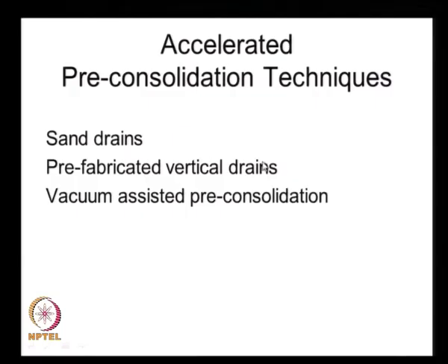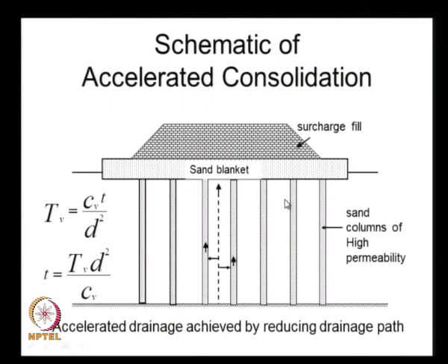Some of the techniques that we can use for accelerating the pre-consolidation of the clay soils are the sand drains. Historically, sand drains have been in use for a very long time, right from the 1920s up to probably the mid 70s. After that we have the prefabricated vertical drains made of geosynthetics, and then more recently the vacuum assisted pre-consolidation. And the approach that we take for accelerating the consolidation is reducing the flow path.